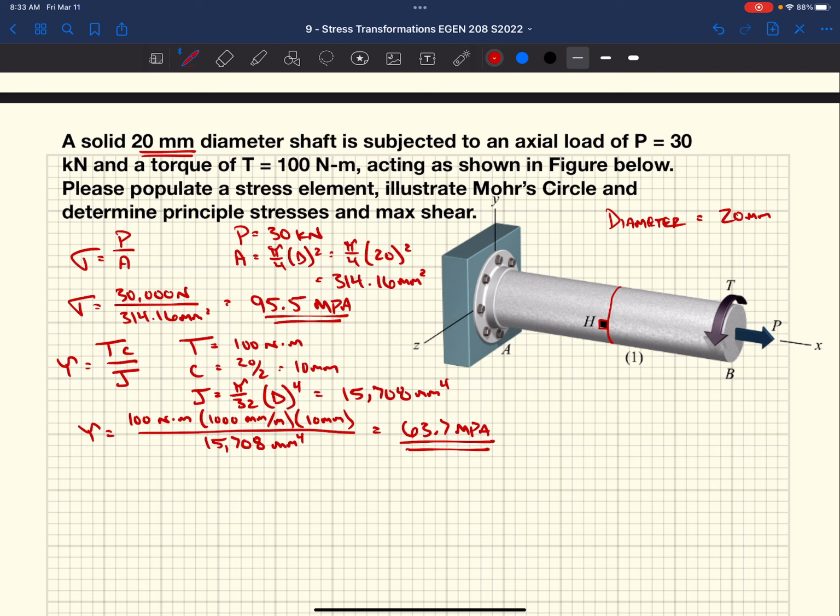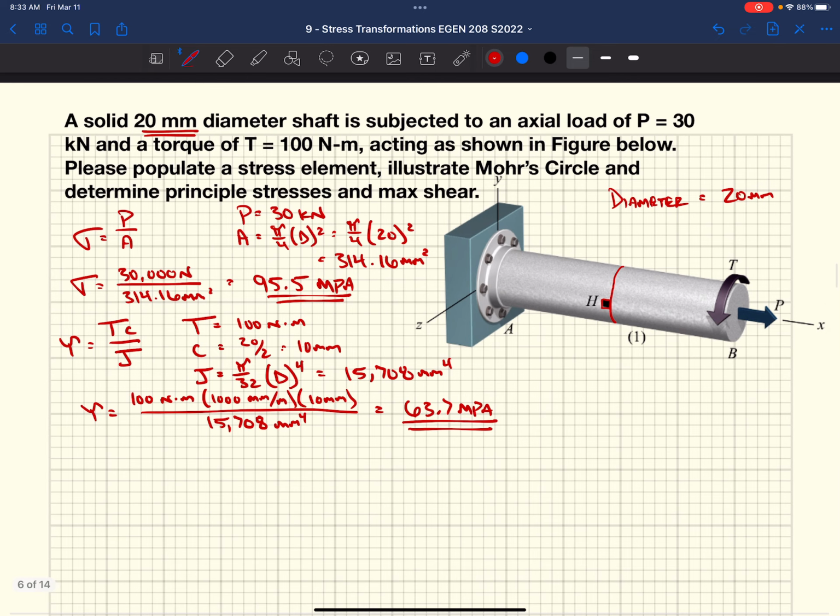And as we know, if we look at this shaft at cross section, it looks something like that. We've got a circle and this overall torque. If we were looking down on the end of this, that torque is going to try and twist the shaft counterclockwise. We know from earlier in the class with our derivations of shear stress that the shear stress is going to be in the direction of that applied torque. So it's going to be doing something like this.